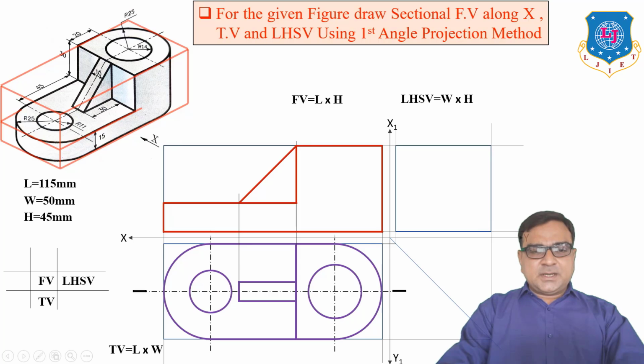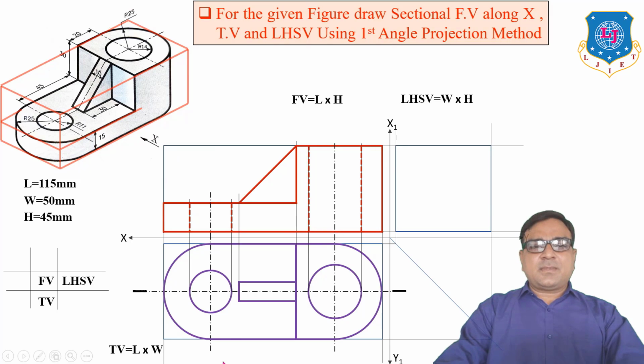Front view of the circle by taking the center line and projection hidden line. Because this is a full front view, this is not a sectional view. From the front you cannot see the hole, so it is represented by hidden lines.